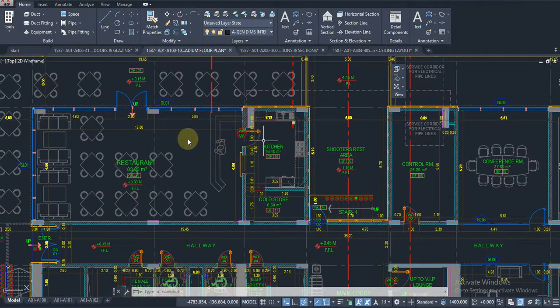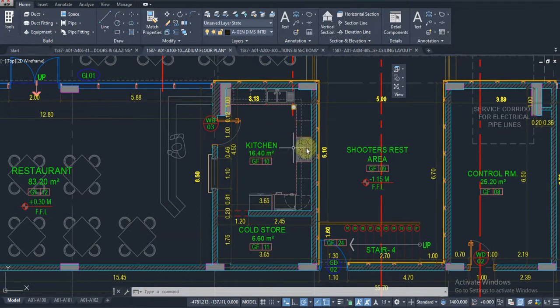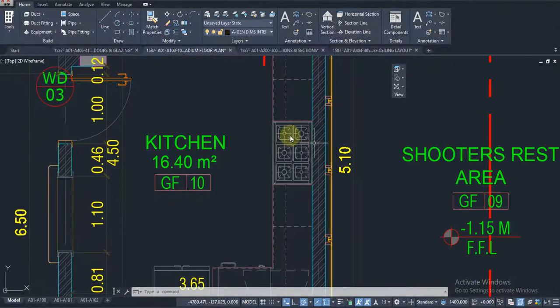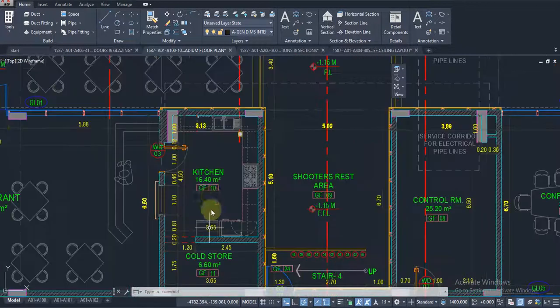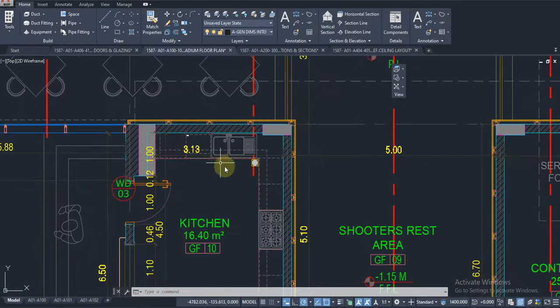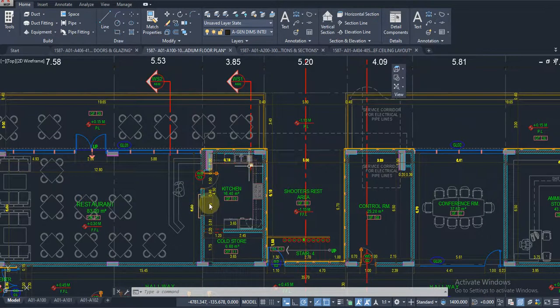If there is any screen in the restaurant, that will come under the appliances, that will be heat gain through appliances. And we have here the kitchen area. We can see there are the kitchen equipments, so we can use the number of stoves here, and we have here an oven we can see. And all these things we can collect the data from this architectural layout.